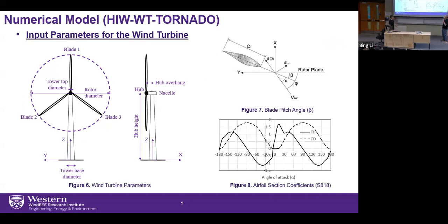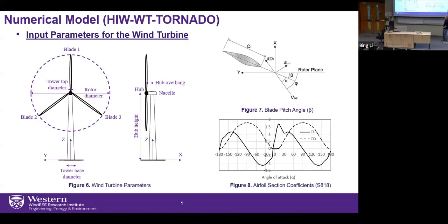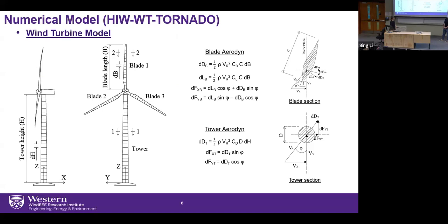So usually, if you look at this blade, when they manufacture the blade, they divide the blade into little elements. And for each element, it comes with one of these. Some of them could share the same graph, but they usually have 4 to 5, or for the 10 megawatts, I believe I have 30 of them. They look similar but different. So the drag coefficient in that equation is here. So we have half times air density times velocity squared times the coefficient, the CD value.